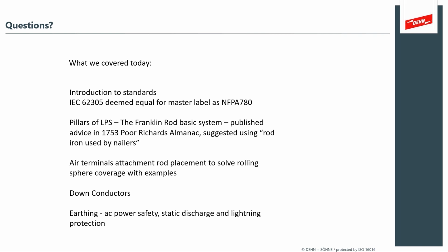Yes, I just want to mention that the only thing the standard says is that if we do use the reinforced steelwork within concrete columns and within the structure itself, we can do an impedance test that way, and the standard does say that needs to be 0.2 ohms. But now is that the 10 amp test? Yes, exactly. That's with the injection of 10 amps.